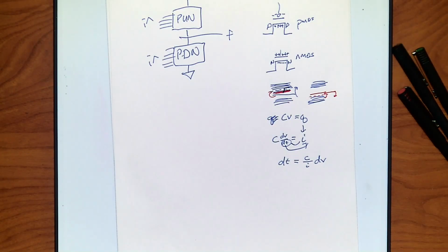As the capacitor gets bigger, what happens to how fast you can turn? Yeah, so it slows down. So I can speed up how fast I can carry across one state, but it takes longer to get it to that full state because the other one was full in a period of time. Essentially, there's almost nothing you can do to make these fast. PMOS is just big. They are just not fast, right? They have their place. They're really good for transferring, so I can't avoid it. But they're big and they're slow.